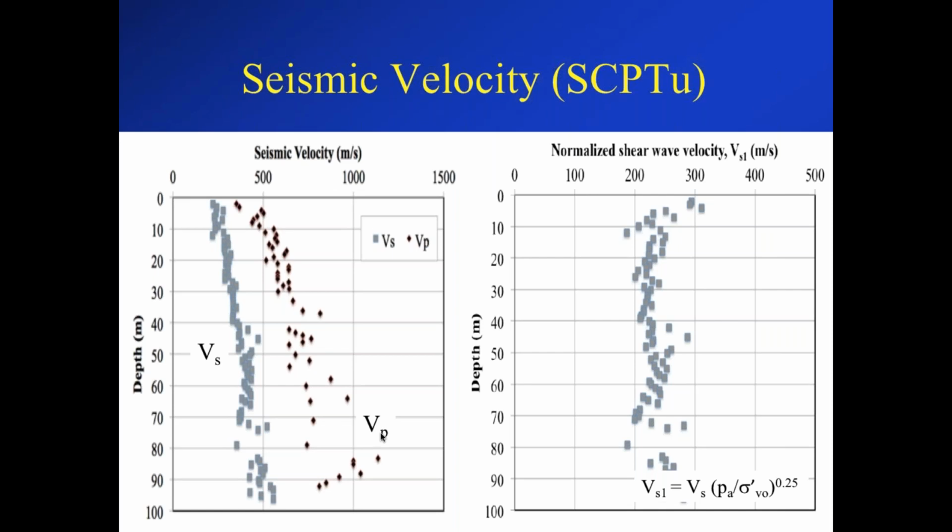There's a phrase used, agglomerated, where basically this rock weathers quite rapidly around its edges, and so it becomes more clay-like. Not on this project; the material here tended to maintain that sort of sandy silt composition, with a fairly uniform grain size.